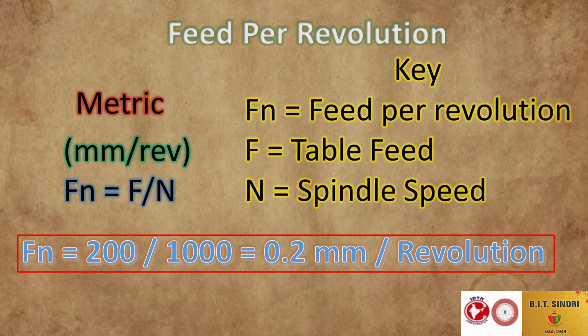So in our table feed, we need to know those variables to be able to complete this, and we also need to have an idea of what our spindle speed is going to be, and that gives us our revolutions to set the machine. When we are using a CNC lathe, I first learned this technique using a manual lathe, to convert a feed rate to work on a manual machine. So let us have a look at another imperial one.